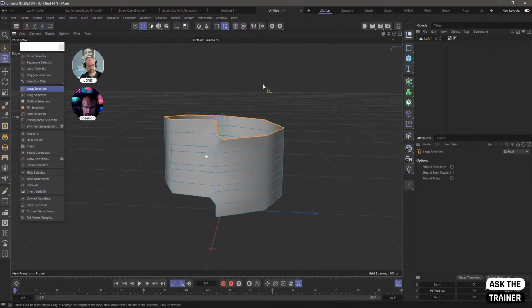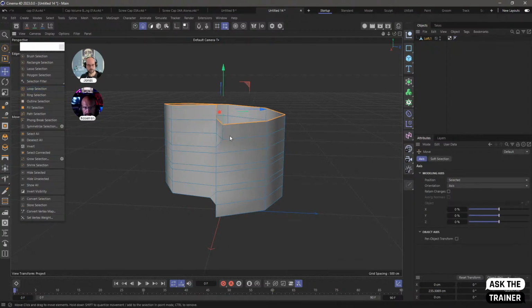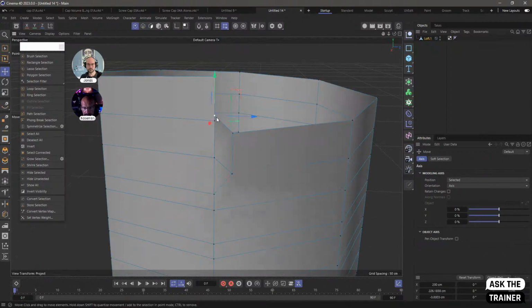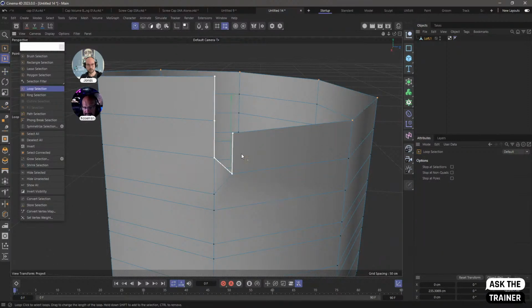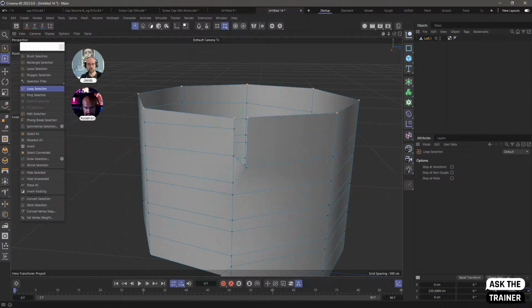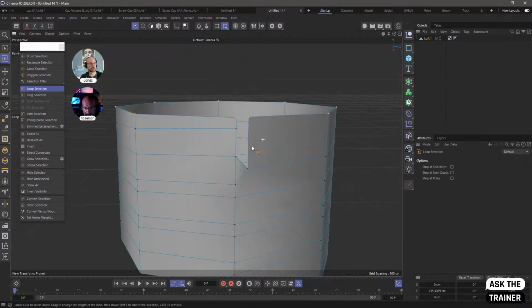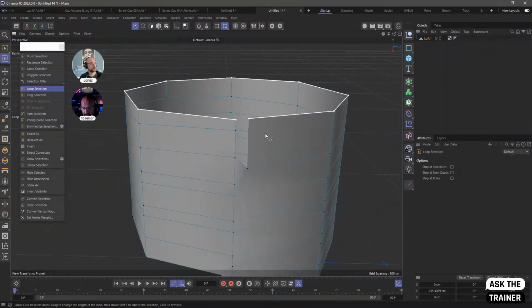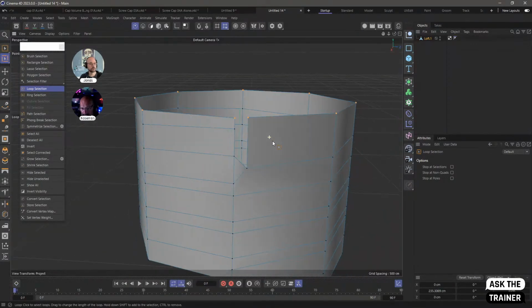The way you can move forward is to make a copy of this so you have an understanding of your topology, and start removing things you feel are redundant. Now we need to get all these points up here on the same level, so go here and set the scale in the Y to 0. Now we know exactly what's going on here. Then you can close this little gap and we figure out the rest as we go.